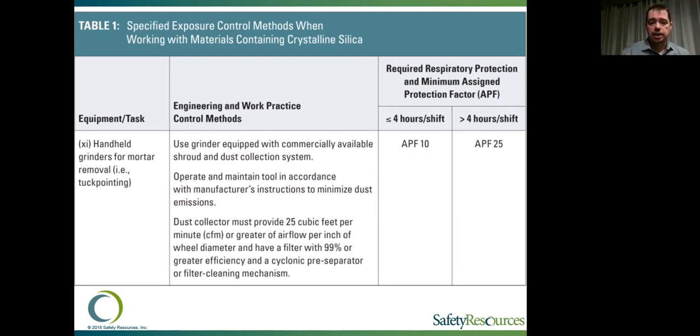Those dust collection systems, and we'll talk about this in a bit as well, also have to have a cyclonic pre-separator or some type of filter cleaning mechanism that allows the filter to remain clean enough so that you continue to get that same level of airflow throughout the work. So occasionally that filter would have to be cleaned.